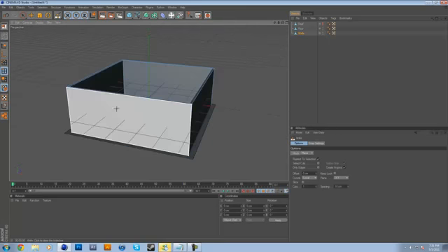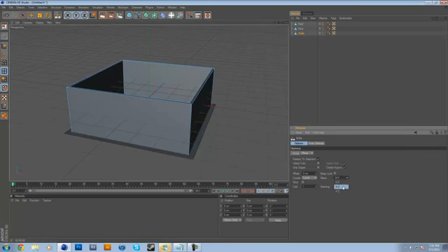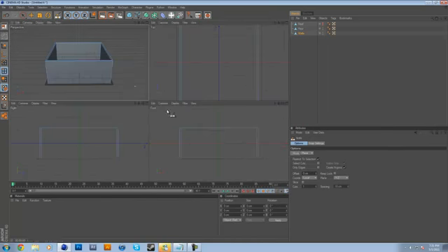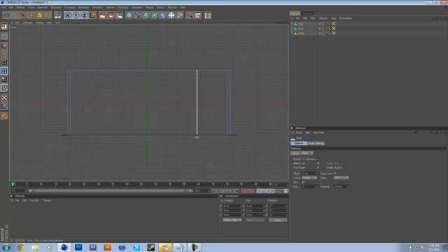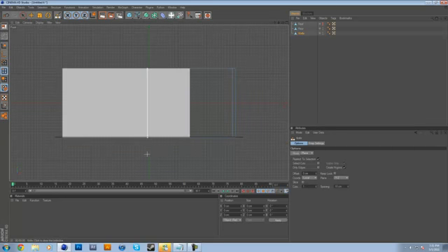So as you can see, we want to cut it on this wall here, so it's actually on the wrong plane at the moment. So we can just change it from XY to YZ. You see that is the correct plane. And so I can sort of judge these up where they should go. I'm going to pop back over to the front view, and just going to pop them in. Try and keep them relatively equal.